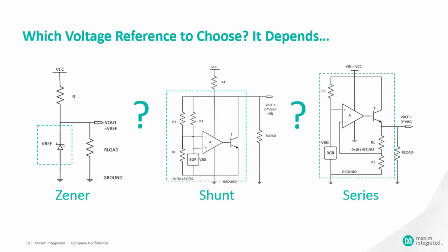For a negative voltage reference, the shunt reference wins because its bias resistor can easily be placed between the IC ground, now minus Vref, and minus VCC, resulting in a reference properly referenced to the system ground. The analogous minus trick played on a series regulator would result in a reference referred to minus VCC, not system ground.